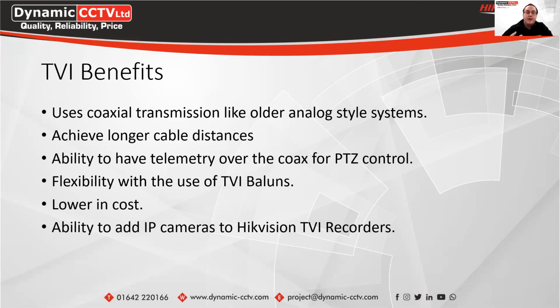And you can use TVI balun, so if you do have existing Cat5 installed or you prefer using Cat5, you can use the TVI balun. There's also now POC friendly balun that we do now sell, which will allow you to use POC transmission with power and video going over your Cat5 cables.